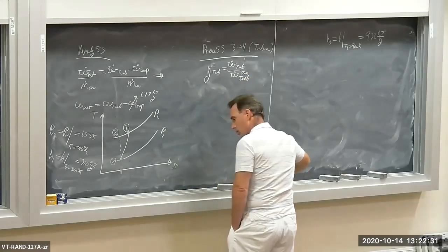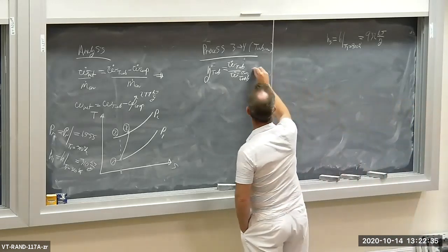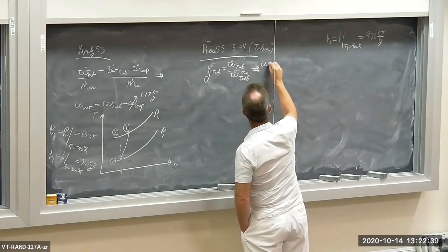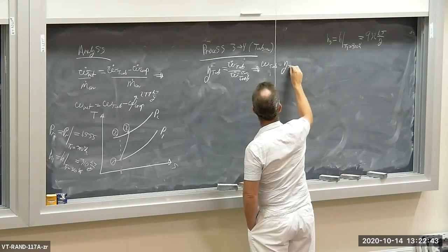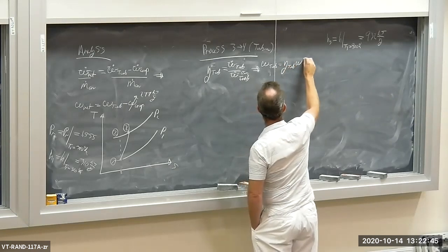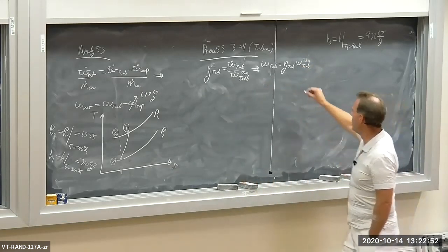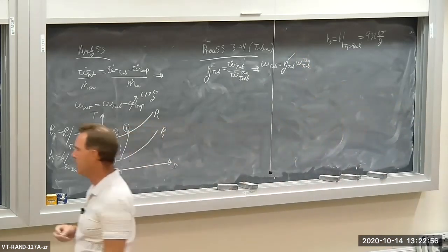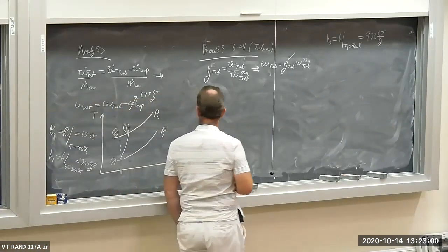In other words, dividing by m dot, W turbine is equal to eta turbine times the isentropic turbine specific work. I know the efficiency for the turbine, it's 86%. So now I need to evaluate the isentropic turbine work.